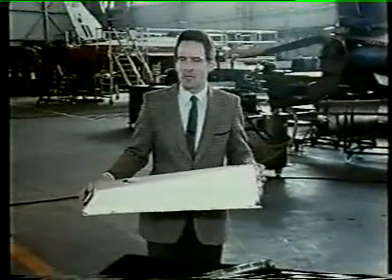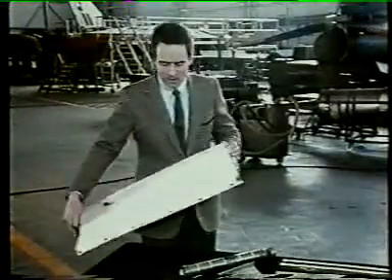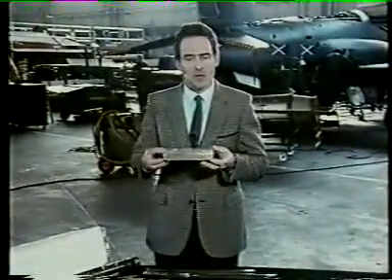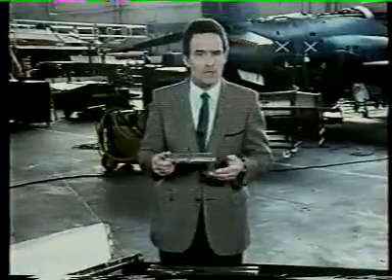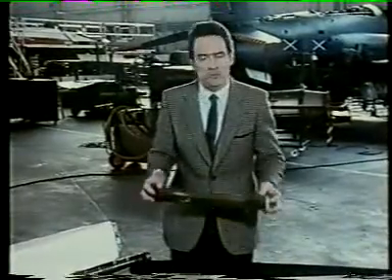We've already considered the problem of dissimilar metals in contact. The effect is commonly seen around fastener holes. Intergranular corrosion is less easy to detect. There may be little or no sign of it on the surface, and the attack is concentrated on grain boundaries within the metal. The corrosion products then force the grains apart, and a great deal of metal can be lost from a relatively small amount of corrosion. In extreme cases, this may lead to exfoliation, a layering and flaking effect.